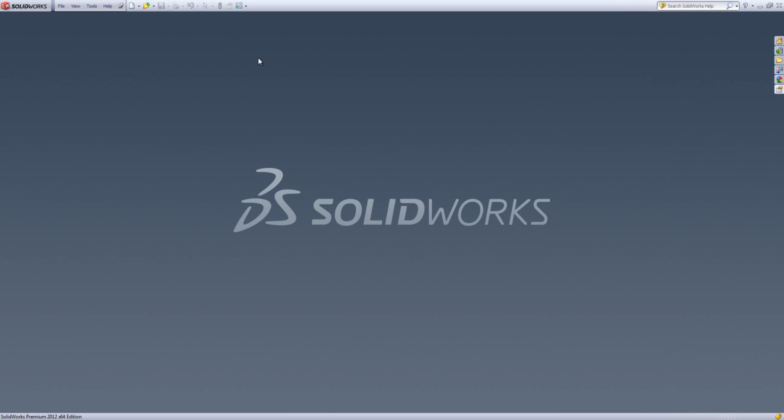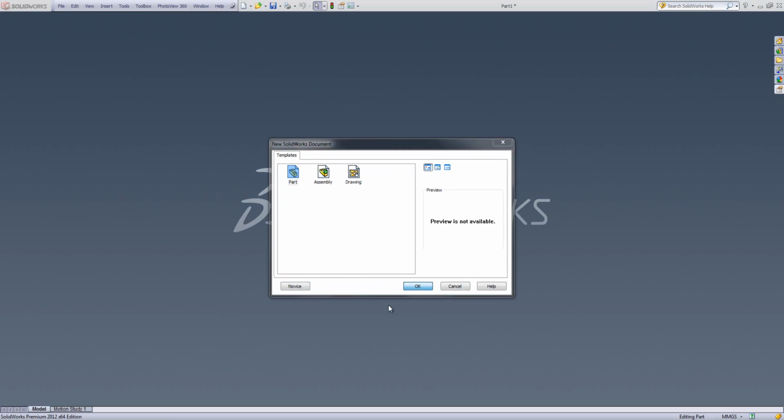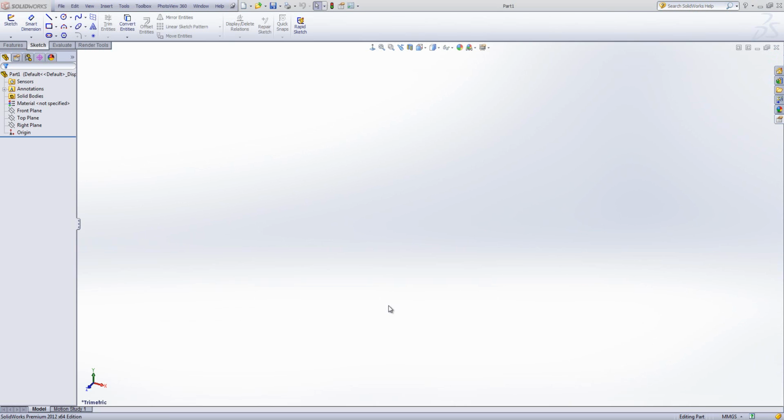And within SolidWorks, we can just start up a new document. We want to start constructing the first of our templates. The first one I'm going to start working with is a part template. So I'm just going to go to File and New, and we can start just from any blank document. When users normally go to File and New, they'll find they have a menu like this one, where you've got either a novice or an advanced screen, and we can just select the part from there to open up a blank document. So this brings in a series of properties and settings that we can adjust.